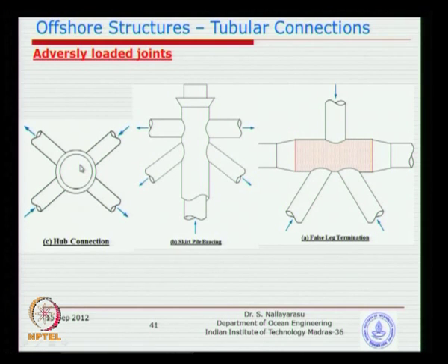If you go and do this analysis by taking this chord and treating one brace by one brace, that is absolutely not correct. Anybody can conclude that, because they are simultaneously applying 2 members in tension and 2 members in compression. So, there will be an effect of 4 times, isn't it, which will not be taken into account when you classify it as a T joint or a Y joint and come up with a design, and basically say the thickness is 20 mm.